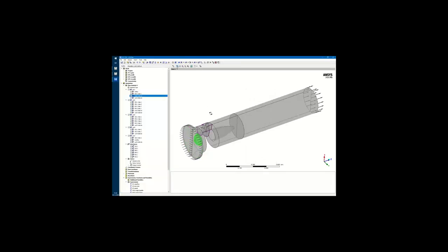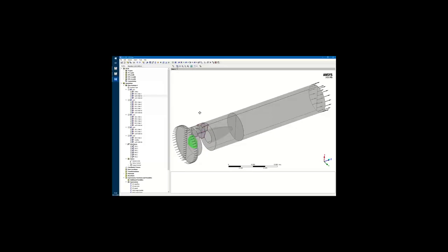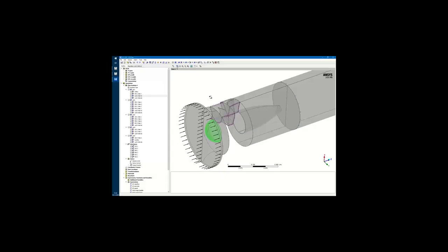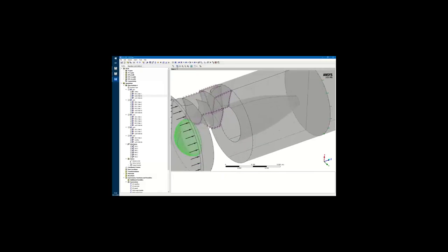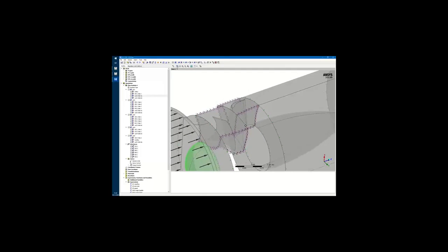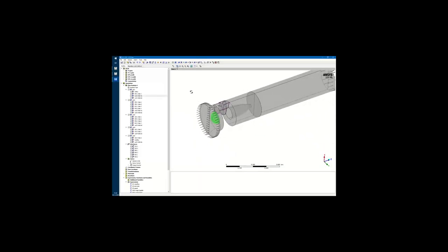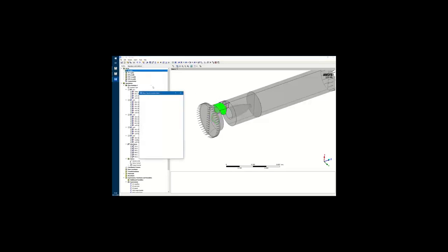As you can see in the model, I have modeled all components as a 360-degree model, except for the blade passages, which have been modeled inside of TurboGrid. And of course, inside of CFX you have the option to quickly modify your setup and make a 360-degree model from your blade passages. This can be done really easily by choosing the transform mesh option.